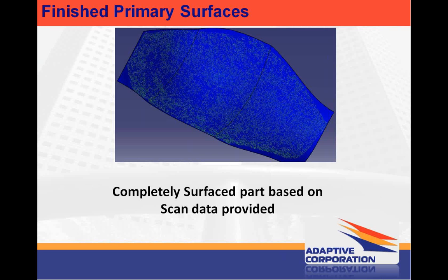The process is not fixed, as there may be curves that drive the surface as part of the initial input. Mylar drawings may also be available to help locate critical features that assist in the final modeling. So not only do we scan the data, we might have other engineering standards and direction that we can tweak the surface even more. And that's all available inside CATIA.